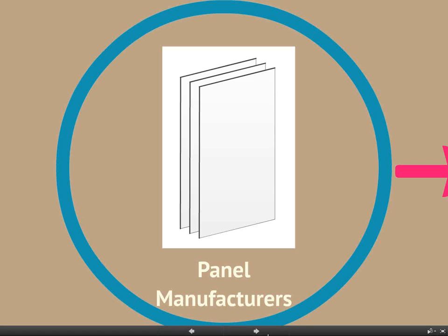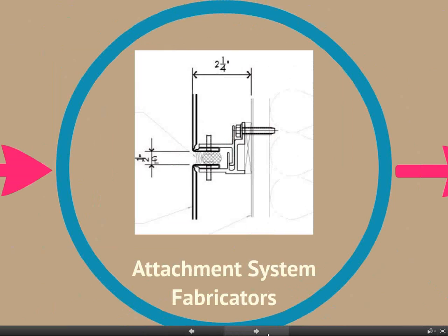And when we talk about ACM or MCM, what form do the manufacturers actually deliver their product? Basically, they're sheets that are 4 or 5 feet wide by whatever length they can manufacture that will meet the fabricator's need to make them into the panels to meet the joining design that the architects have come up with. Right. So they are just flat sheets. Just flat sheets. So that's a really important distinction, that the manufacturer, especially if you're naming manufacturers of the flat sheet in a specification, you're only naming that particular product, not some sort of a fabrication.